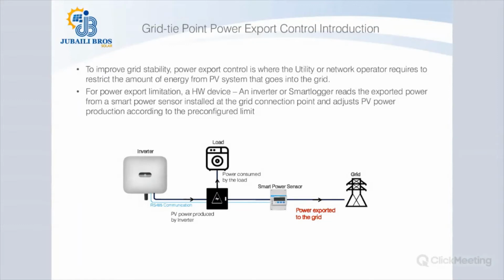And this is for ensuring higher safety and higher stability of these grid connections by network operators. So Huawei actually provides active power limitation options, whether based on unlimited power or zero export or limited power at the grid connection.